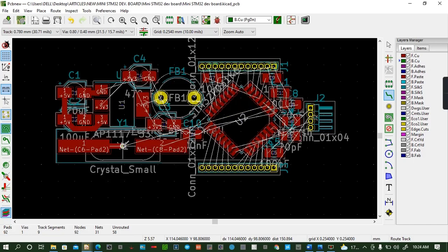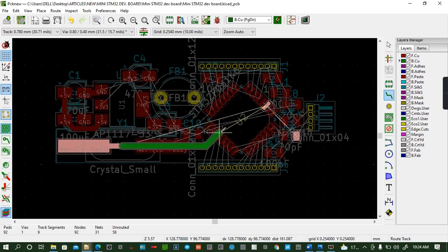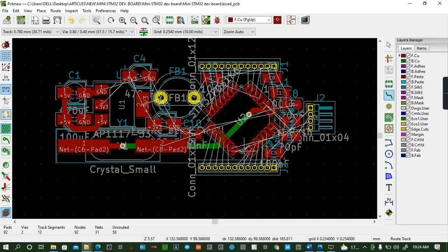Like that. Then you go to the bottom layer. You go like that, and then you can place a via to the point you want to come up. Then you finish up your sketch like that. Control save. You go to the next part.